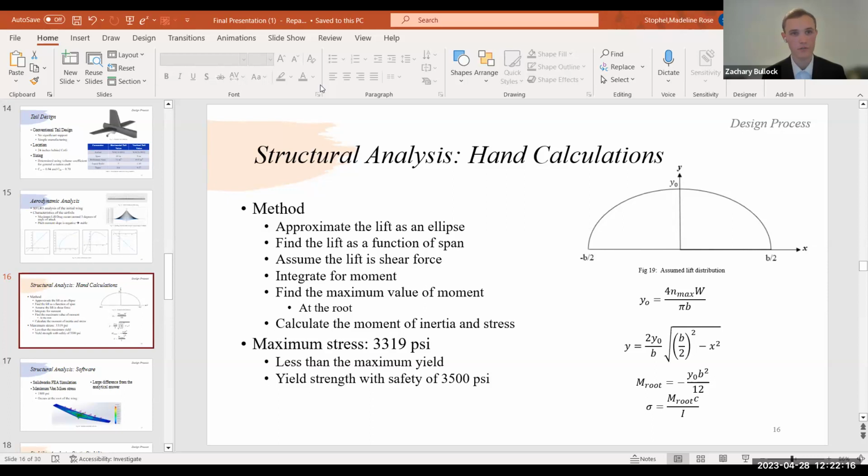It's definitely going to reduce the effective yield strength compared to just a casted piece of PLA. Yeah, so that's something you should consider when you're doing these initial hand calcs. I don't know if this is an adjusted yield strength, but it is. We used a yield strength in the lower 10% of data that we found from studies on PLA yield strength.